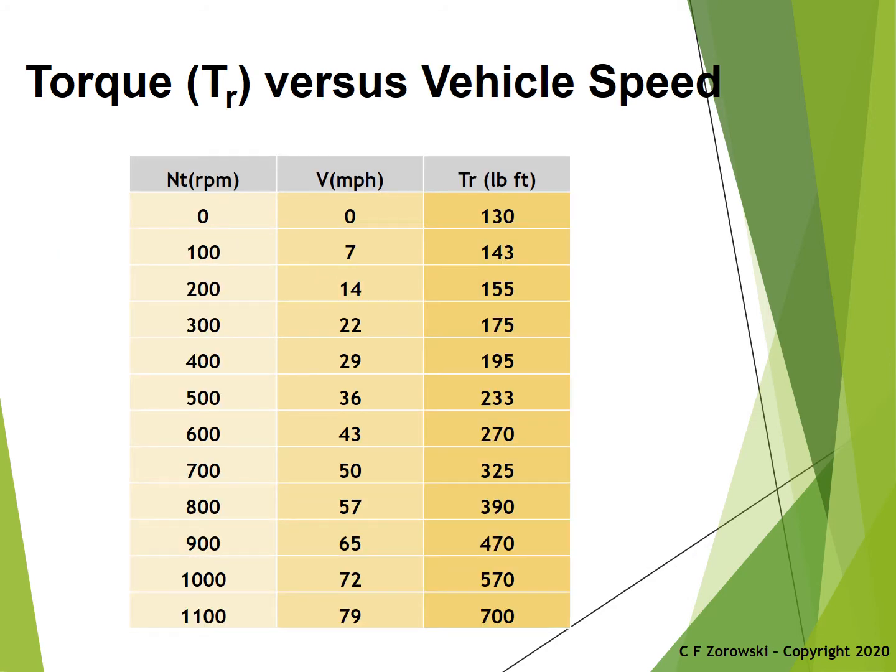The solution process now returns to step 4 to determine the maximum velocity of the vehicle. This is now easily obtained by plotting the torque required at the rear wheels as a function of vehicle speed on the previous torque graph.